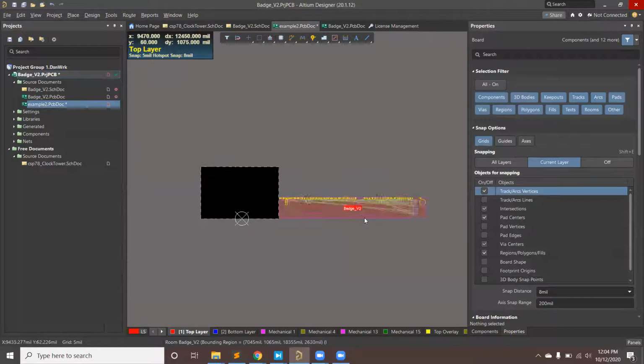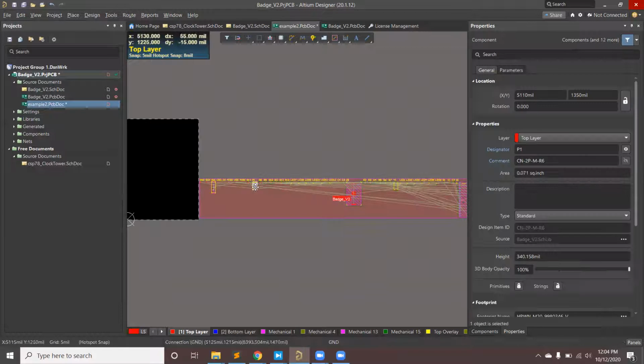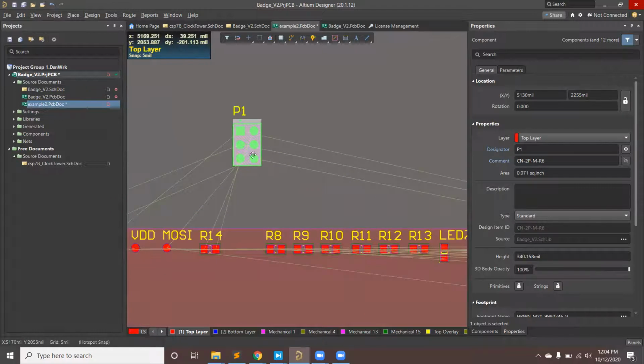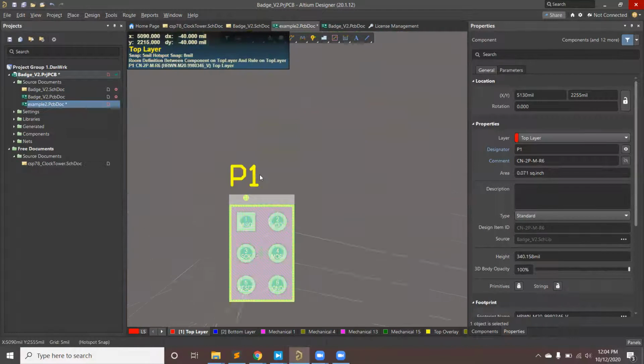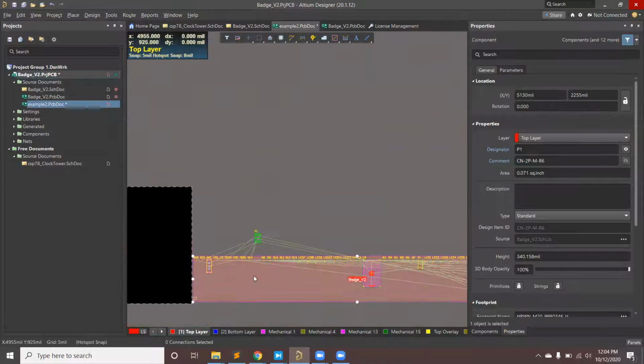It's gonna be fine. And what that's gonna do is create this big room. And basically, if you try to move a component outside of that room, it's gonna be an error. You can do it, but then you'll see it's green. For some reason in Altium, green means error. And you see those problems. You're like, what's wrong? It's because you just moved it outside of the room. Rooms are stupid. We're gonna delete that.